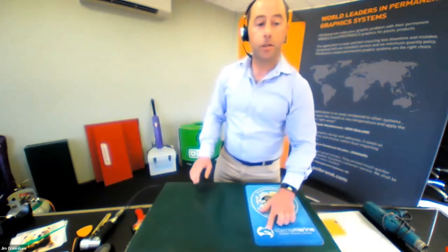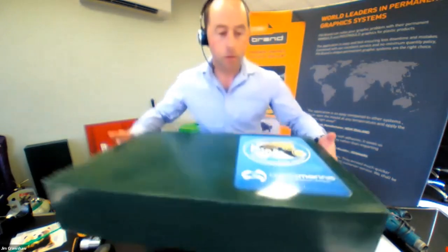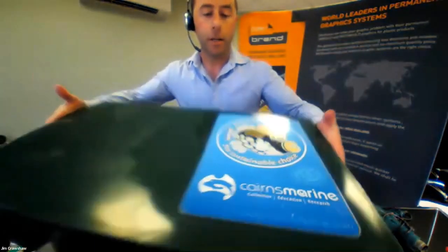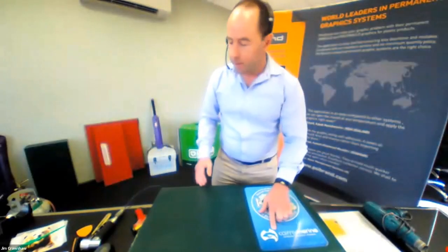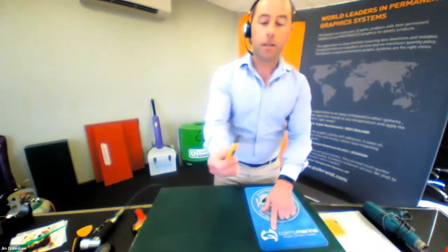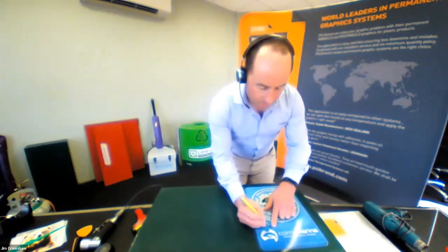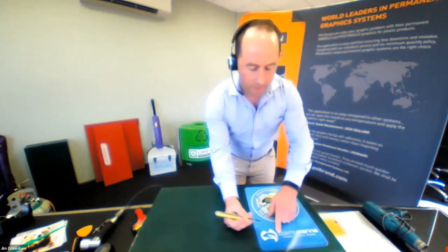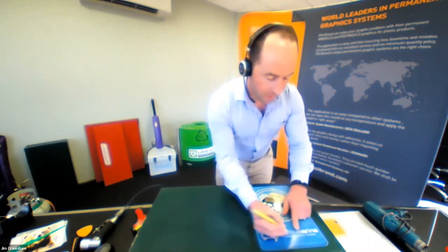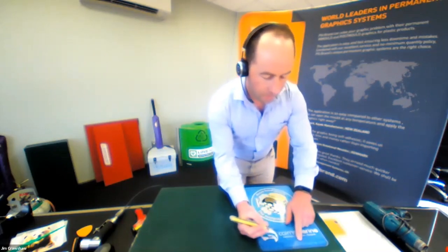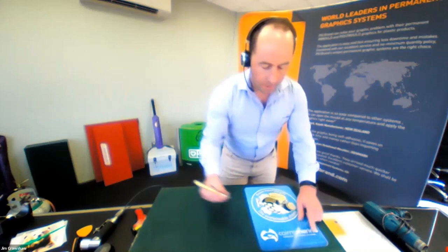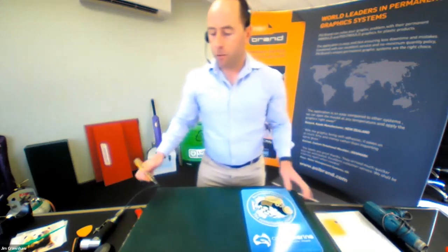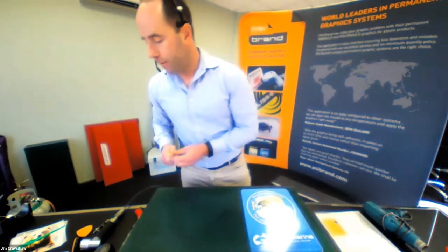Now, like I mentioned, I've trapped a couple of air bubbles here. I'll try and show them on the camera. It might be a little bit tricky to see. But when you get a trapped air bubble like this, you just need to get a knife or something like this and just lance it, and then press the air out with your finger like this. Another one down here, get rid of that. Now I've got one here. I'm going to leave it just to show you what happens when we do our final flame.